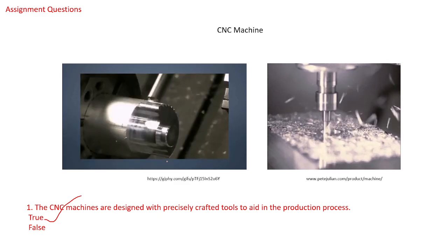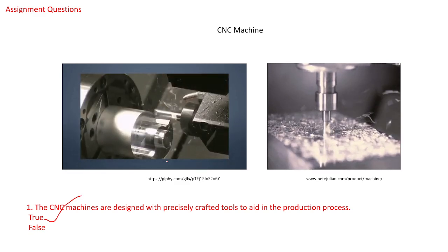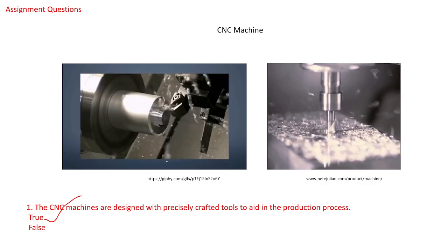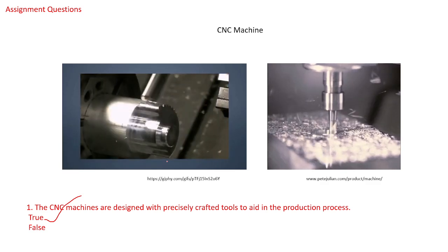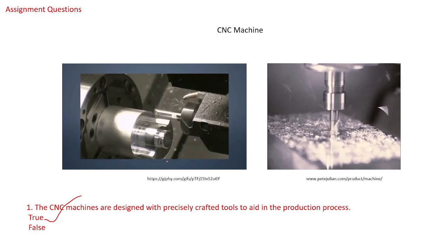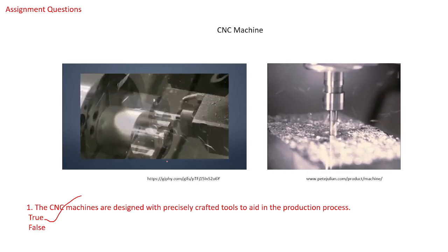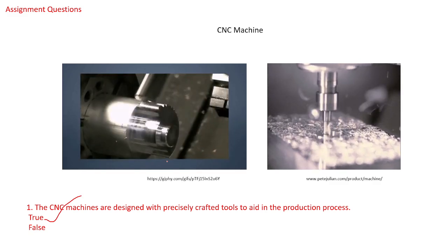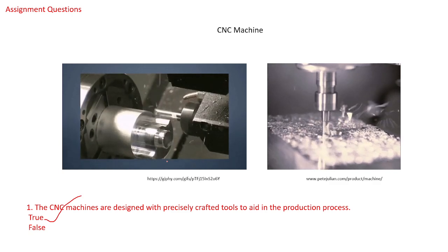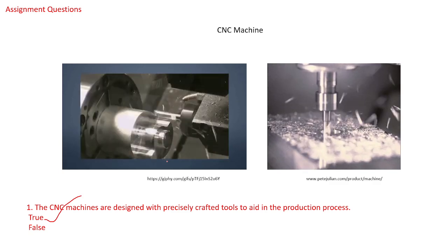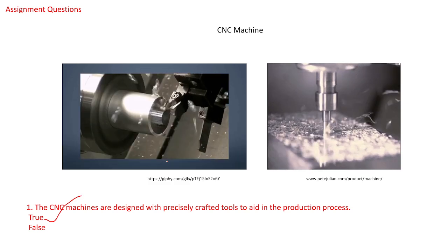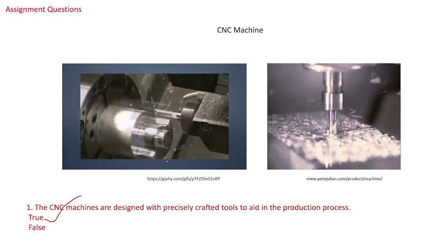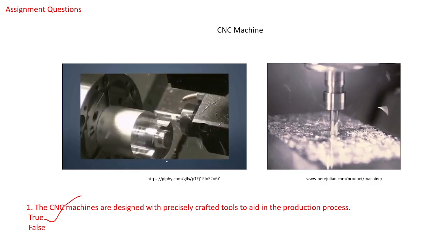And then the CNC program. Before starting the operation you need to upload the CNC code into the machine, and you need to keep two variables in mind at that time. The first one is turning speed, which is basically the speed at which the workpiece rotates, and the second variable is the feed rate, which is nothing but the speed of the cutting tool as it moves along that rotating workpiece. Okay, and then you need to take care of the CNC turn part loading time, cutting time, and idle time.